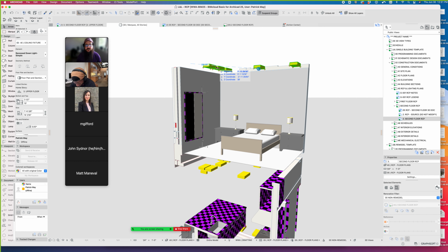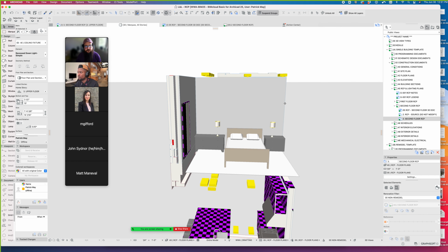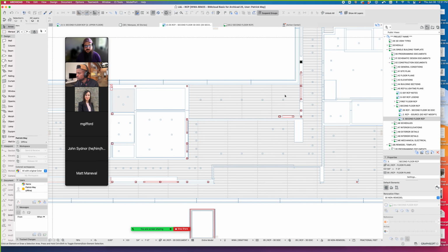If we have an IFC file from the engineer, we want to make sure that we don't have a recessed can running through a major beam, or that it's all coordinated with the joist layout and things like that. We can't do that if it's 2D only, so having these as 3D elements is useful. But when we used to place those here in the 3D document, they would show up as a symbol, but they wouldn't actually track through to the 3D model. So that's where you'd have the redundancy.